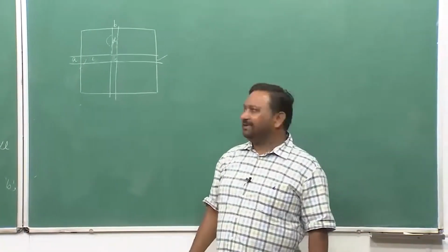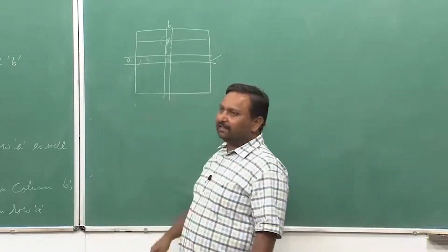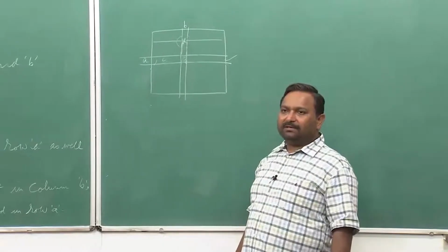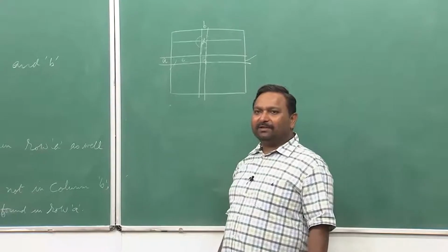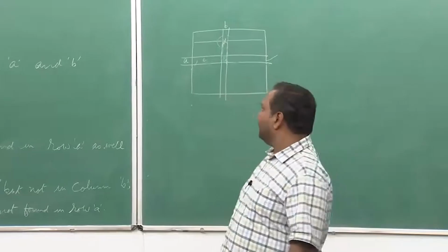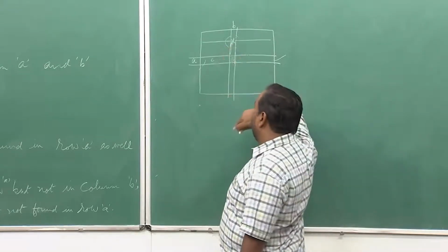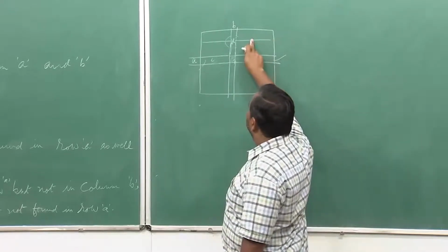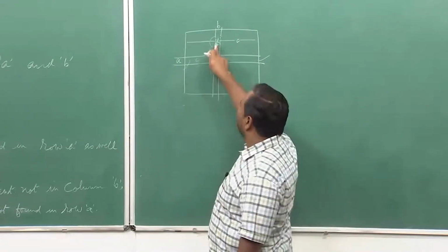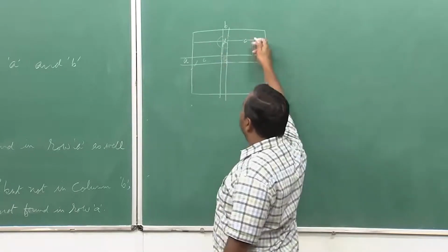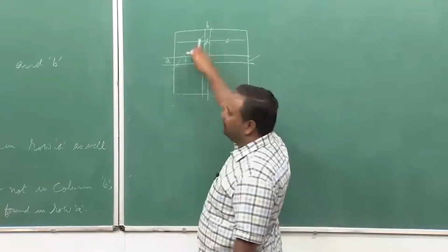So, now what to do? The way the rearrangement will happen is, I will look into the row where this D is. Remember, there is no element which is duplicated; I am talking about unicasting connections. Everything is unicast, there is no multicast. So, D cannot repeat anywhere, there can be only one D in this place. This actually means I have to now look here for wherever there is a C available. Remember, C was not there in the column, C was present in this row but not in the column, and D was not in this row, so it was in the column.